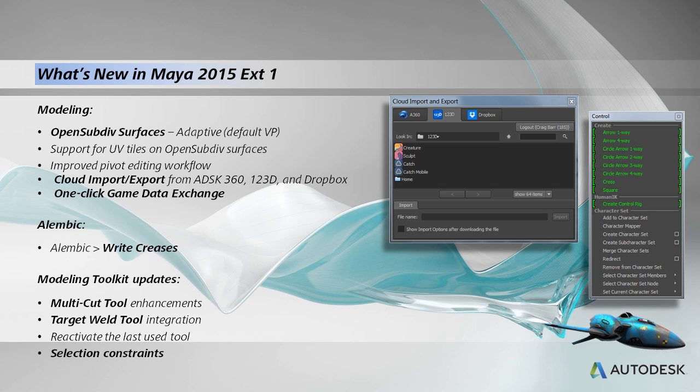modeling. Within our OpenSubdiv surfaces, we've added adaptive, and that will actually work in the default viewport as well. Support for UV tiles for OpenSubdiv surfaces, which is nice. Within the modeling world here, improved pivot editing workflow. This is really nice. This is where you can customize your pivots to just about anything else. So take an object, and grab a component from another object for that matter, and use that to drive your pivot. And you can do this on the fly as you model and work on any object now within Maya.